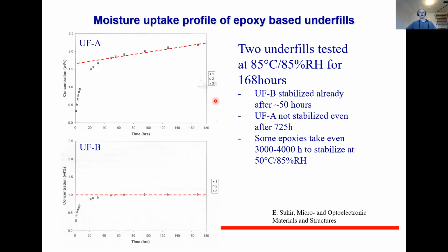But they didn't consider that the 90 degrees Tg is defined in dry conditions. So now when you put it in hot and humid conditions, the moisture penetrates inside and decreases the glass transition temperature, and it decreased more than this 5 degrees.